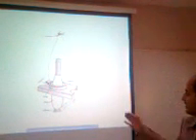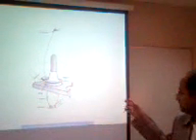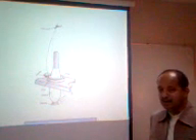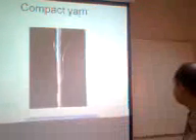spun. In case of combed yarn, we first make the comber lap, then it goes to the combing machine, and next is the drying process, and again the roving and the spinning. Here is the image of the ring spinning machine. You can see the package size is very small in this case, but the quality of the yarn produced is even better than all other types of yarn.